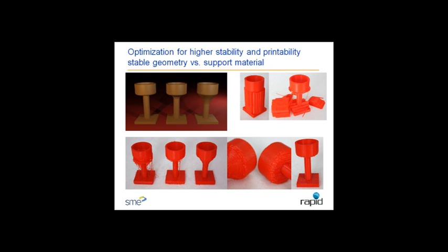An example of a task which can be demonstrated by the student is the 3D printing of a candle holder, let's say starting from a geometrical shape on the upper left corner of this slide. This geometry includes some overhanging parts which drop during the printing. Of course, in this case I'm talking about the FDM or FFF techniques, and the material is usually PLA or ABS. Now there are two approaches to tackle this problem.